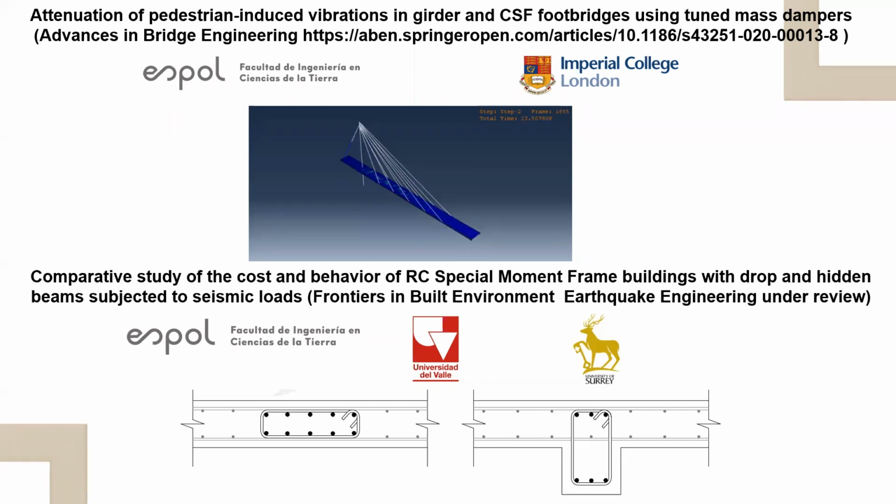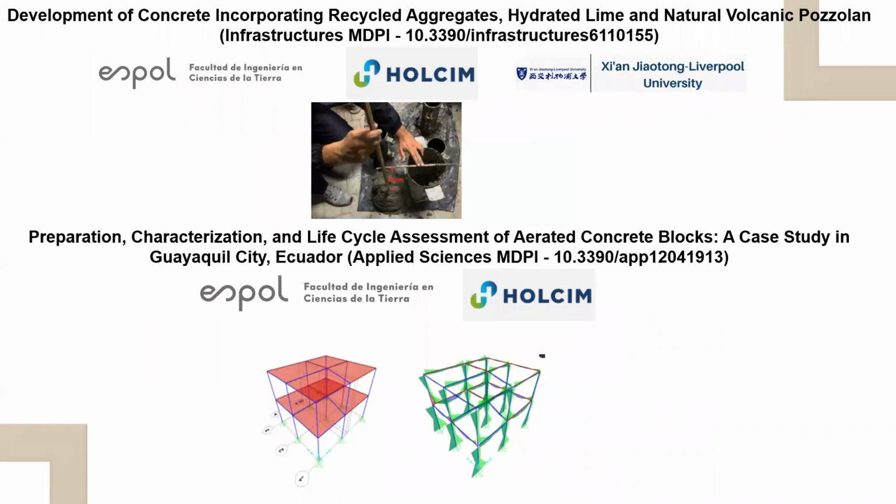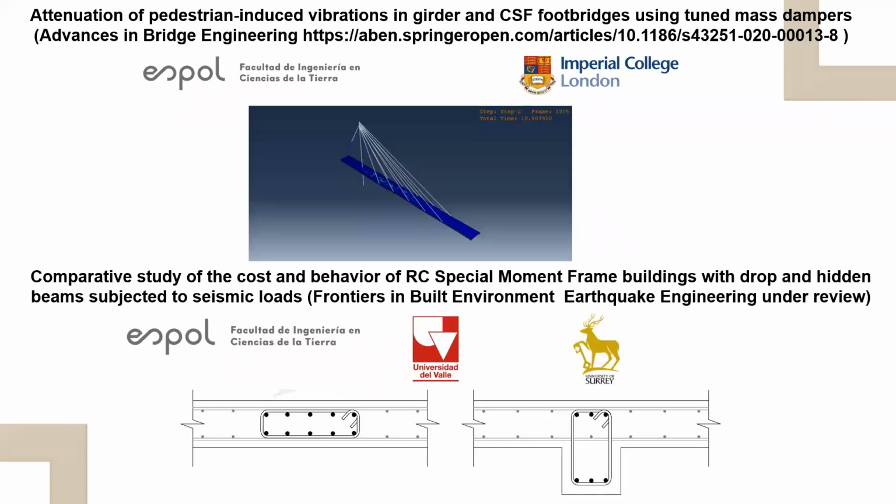And after that, we have made some design recommendations on how to employ this tunnel mass damper: how many we can employ and where, because there are no guidelines that say, depending on the structure, you can use it in the center or in the corner, etc. So we have studied different configurations of this tunnel mass damper in order to construct a slender footbridge. We are talking about main span lengths for cable-stayed bridges from around 50 up to 300.